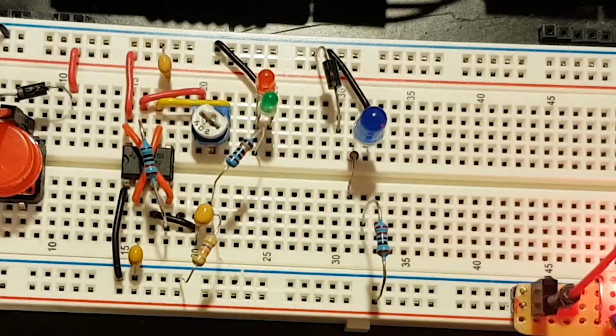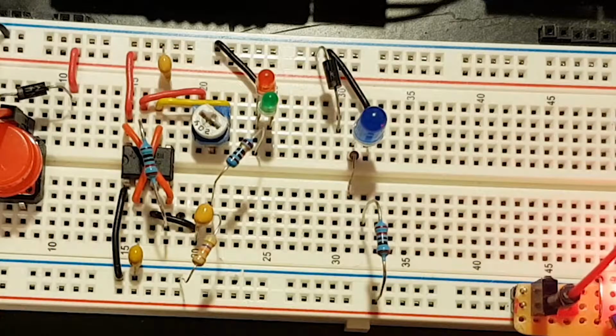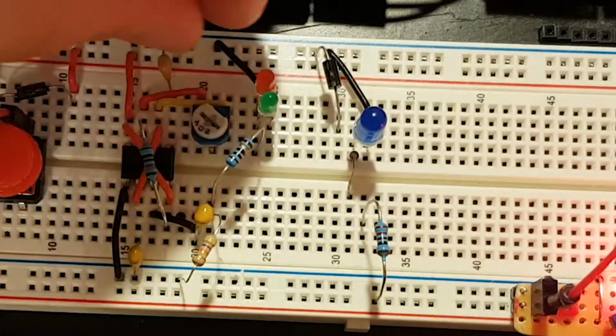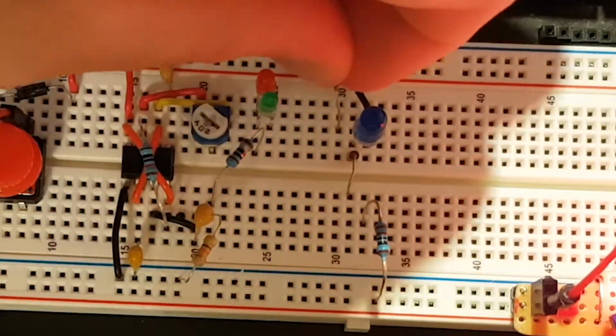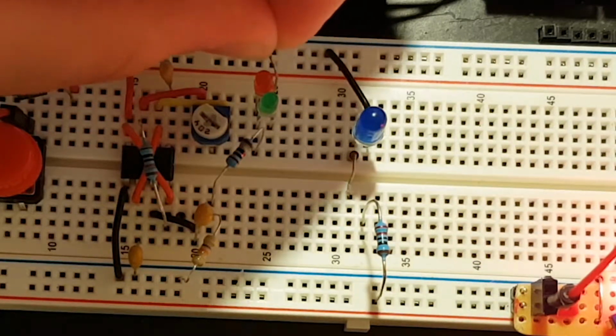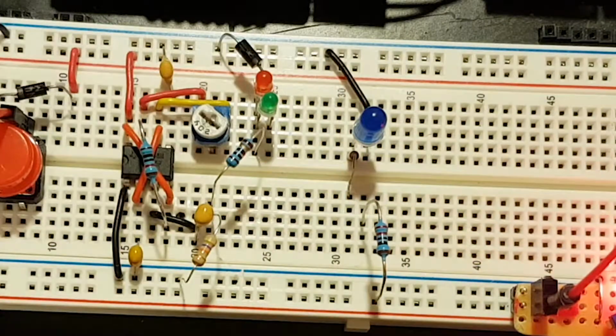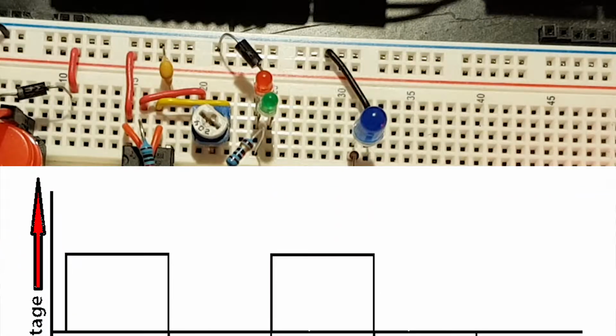On the breadboard this time we have the 555 timer circuit generating an alternating current. Connected are 2 LEDs, and we can see the LEDs are alternating. Now if I change the ground wire for the LEDs, take that out and replace it with a diode, you'll see only one is flashing. We have taken away the negative part of the alternating signal.